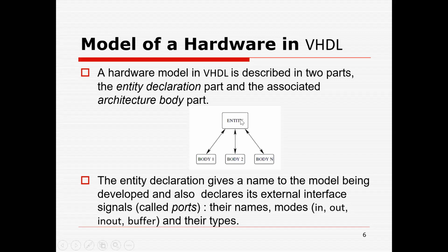But you should have an overview, like if you are defining an AND gate, the simplest entity. This unit, the entity, will only define that there are two input ports, and there is one output port. That is all you are defining. The inputs are Boolean or bit. We will see what is the difference between Boolean and bit. And your output is also of the same type, Boolean or bit. Again, just one.